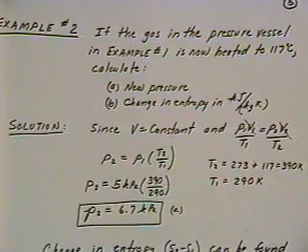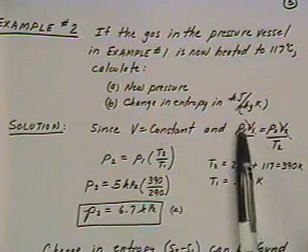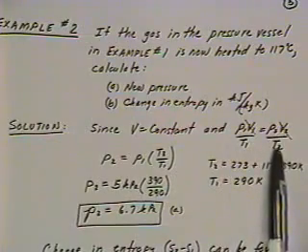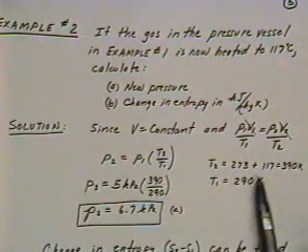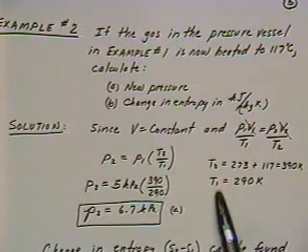Okay, so we can go back to our perfect gas law equations. Remember on the previous page we had the relation on the gas laws that P1 V1 over T1 is P2 V2 over T2. In this particular case, since we're working with a container that's a rigid container, the volume stays constant. We're not doing anything to the mass of the container or the volume, and so we can then cancel out our volumes, and we have a straightforward relationship then that P1 over T1 is P2 over T2. We know temperature is 273 plus 117, which is 390 for the T2.